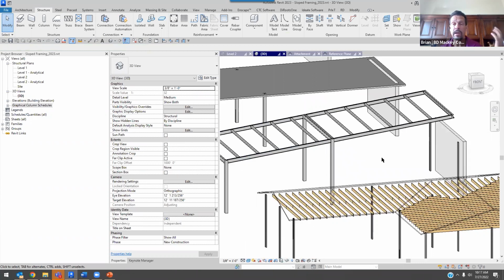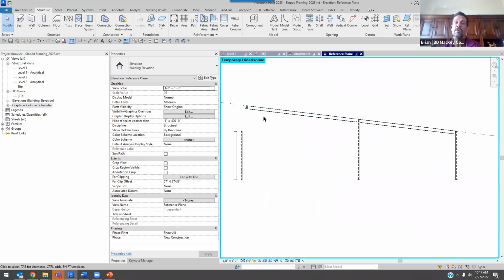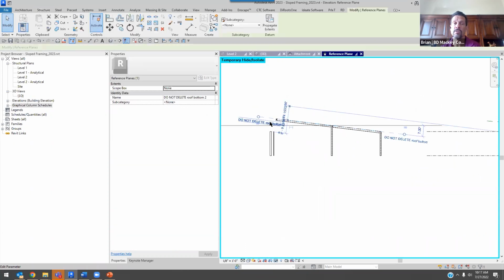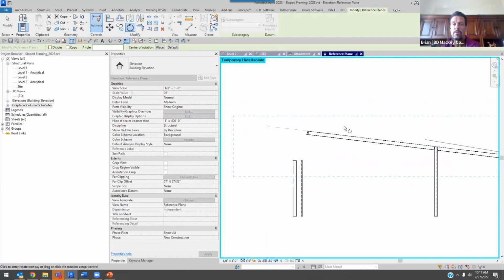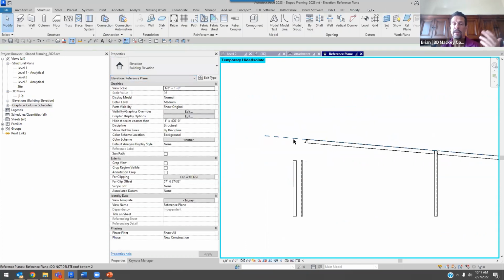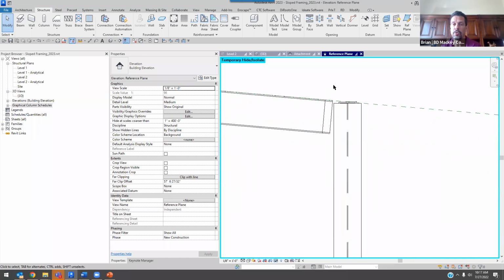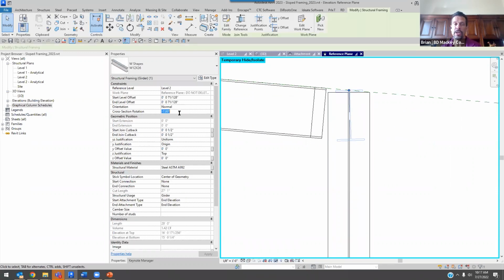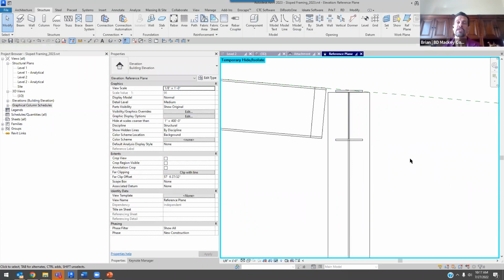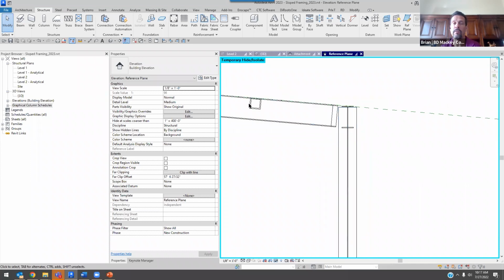The other disadvantage or advantage, depending on how you want to look at it, is if I'm in that view and I want, again, like you saw, to rotate this, I want to change the slope. If you've used a reference plane, you have to come back and use the rotate command, right? Where am I rotating this from? Again, you might be doing it here. I'll come over here, just say, hey, it's going to be 2 degrees. And now I've sloped it back down to that 5 degree I was before. But again, oh shoot, go into wireframe. This one had a 7 degree value in it. The plane changed. So now I've got to go through and make that be my -5. So this, again, just trying to show you, it can be advantage, disadvantage, however you see it, what you're looking for, but all those beams are going to be perpendicular that are associated to it.